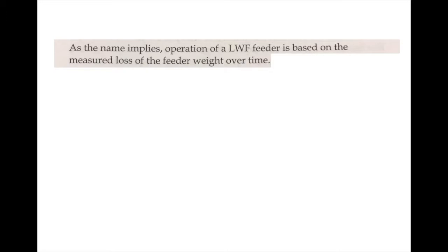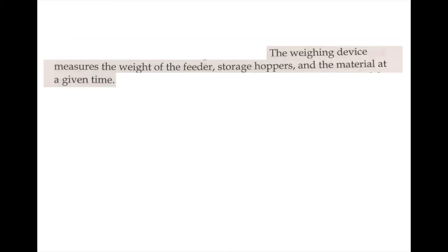I've had times where we are making a batch in a big tank where we're adding in multiple liquids and powders, and we want to know how much is in the total batch, and we'll look at the weight before the batch is made and also ongoing as the batch is being made, and that difference is called the gain in weight. It's how much is in the tank. So that's a gain in weight strategy as opposed to a loss in weight strategy, which we're talking about here.